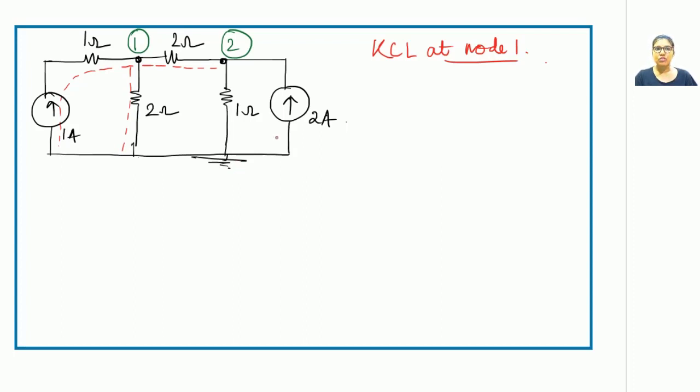In these questions, we have current sources. There is one thing that you need to know when you are dealing with current sources. What was our basic assumption? Our basic assumption says that the current should always flow in the outward direction, which is true. This is our assumption. However, if a current source is present in a particular branch, then that particular direction of the current source is to be taken into consideration.